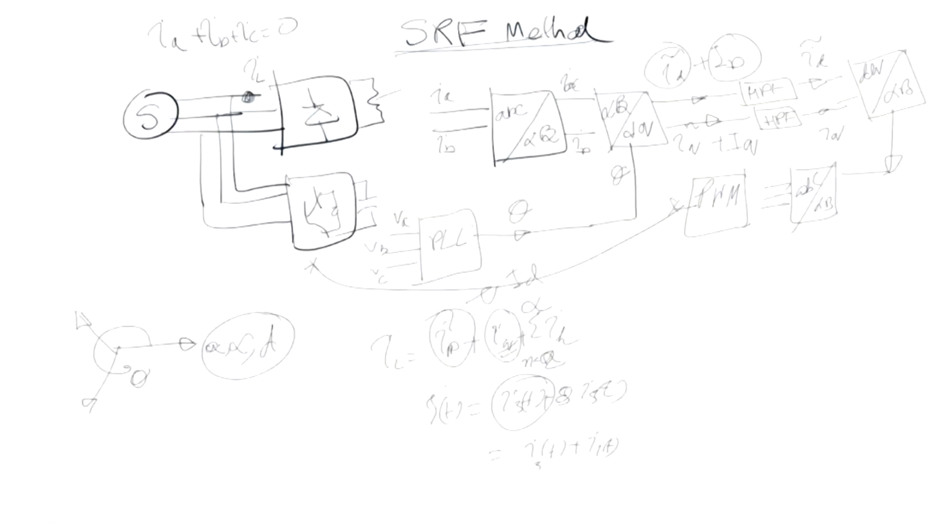So, then we have to generate another sequence, theta and minus theta. So, then the PLL has to perform differently. Since the D is something rotating in a synchronous frame, once you have a positive and a negative sequence, the positive sequence will look stationary, but the negative sequence will be rotating at a speed of 50 hertz opposite to you. So, it will appear as a double frequency harmonic.